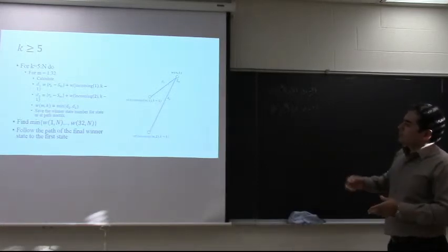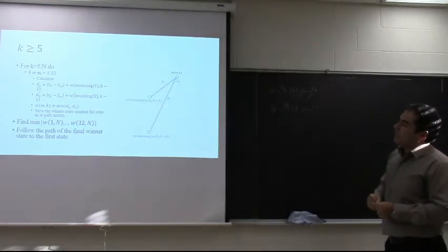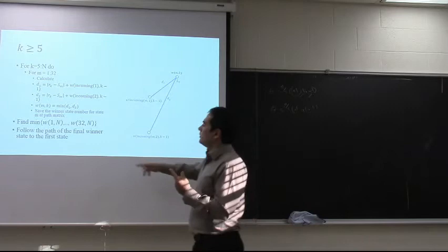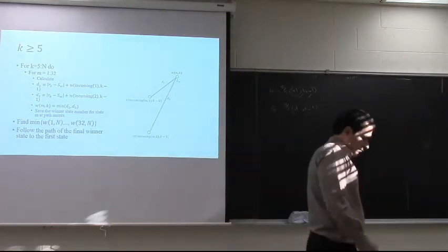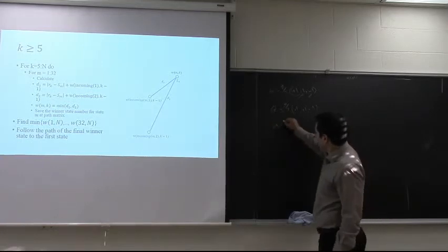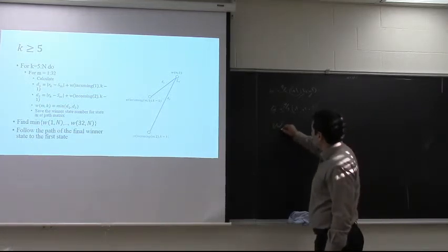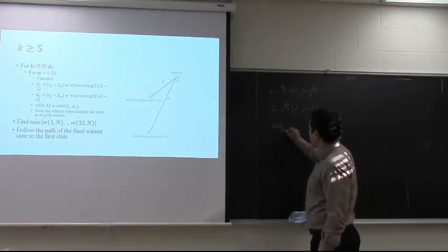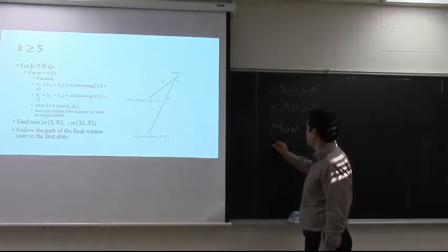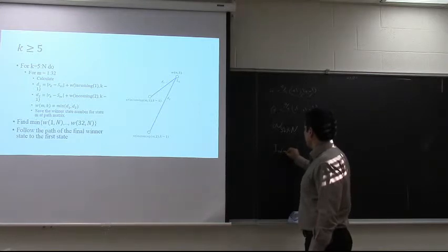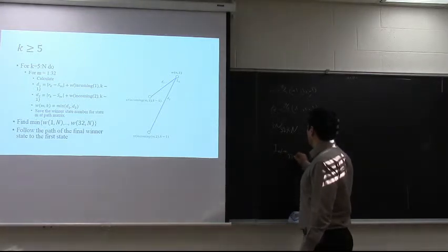Therefore, again, like the maximum likelihood sequence detection for the system with memory, not the GMSK one, you need to create a W, which is a matrix of weights. Let's call it 32 plus n, and also an index matrix, which will also be 32.